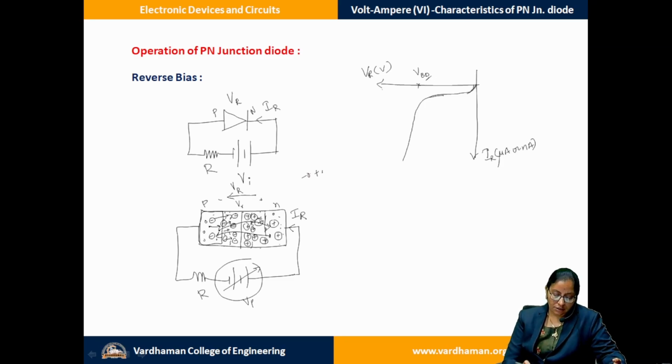So continuously this particle concentration increases, which implies that your particle concentration gets multiplied as we try to increase slightly beyond it. That is what we call avalanche multiplication. They go on multiplying, because of which the breakdown occurs and the current increases, because the majority as well as minority carrier concentration is increasing. So your minority carrier current rises suddenly when you try to apply more than the breakdown voltage. So this is a point where it has to be stopped, that beyond this reverse voltage there is a possibility of damage of the device as well.